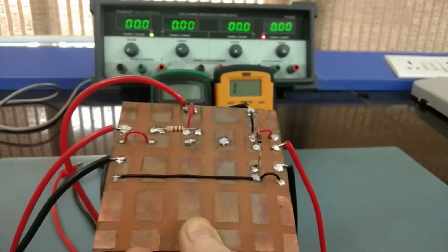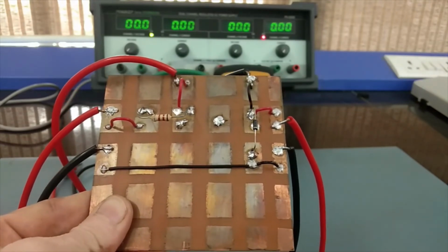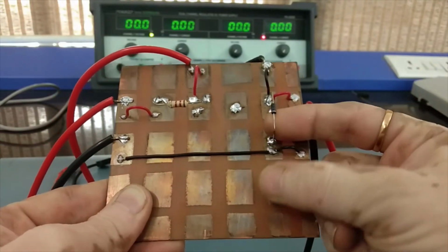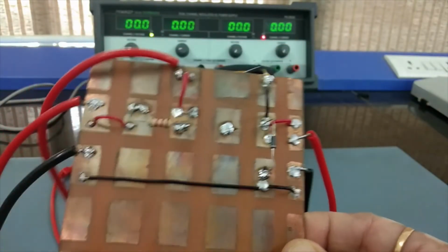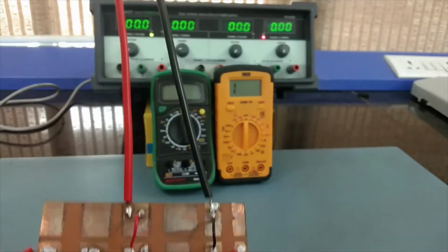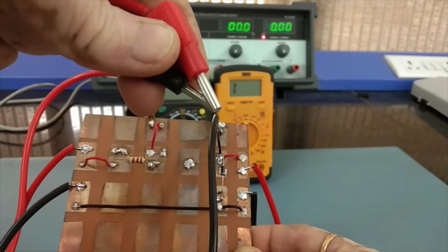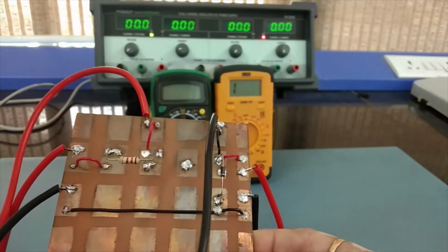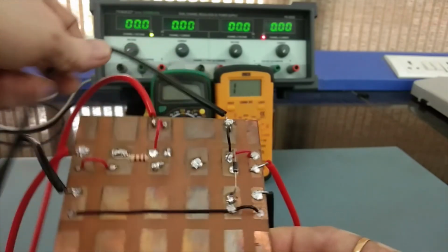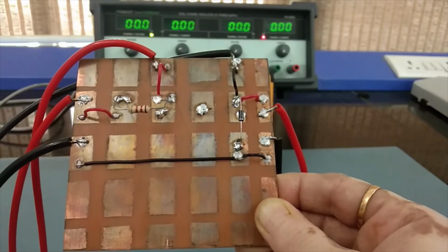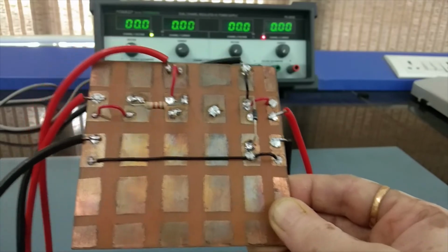And when performing for reverse bias operation, we can simply desolder the diode and change its orientation. And these two wires you can find, if we short these wires, then current will pass through it. However, since we have to connect the ammeter in order to measure the diode current or the circuit current, we will use these wires to connect to the ammeter.